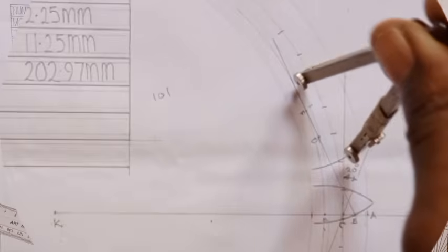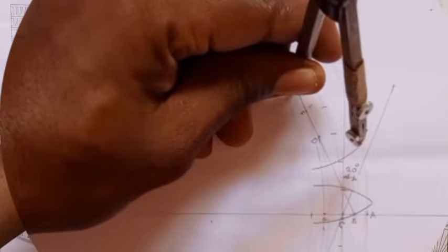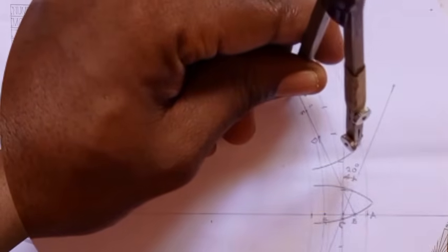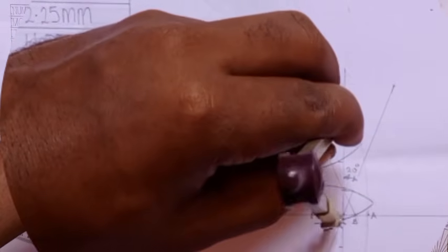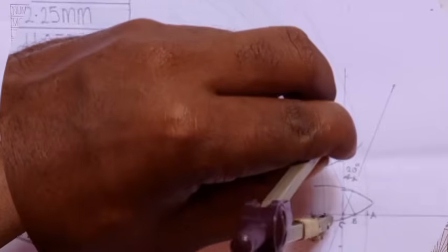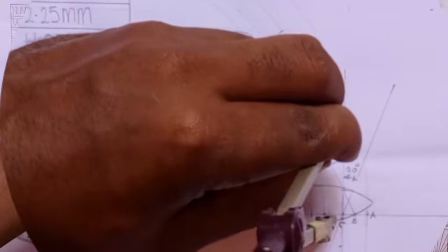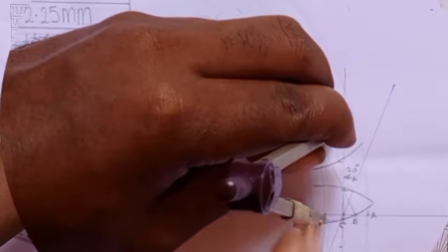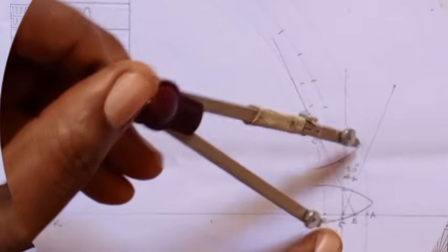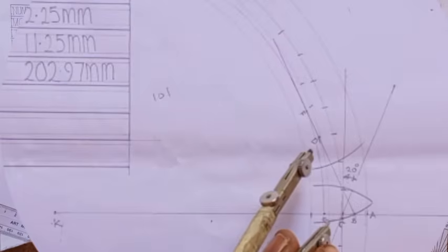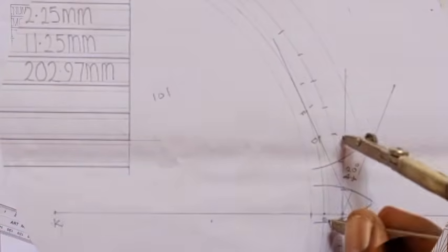You can see that? Now look, the pencil now is facing the right hand side here. So I'll still come to the second point again. I'll mark on the right hand side on that radial line again. Right? If I mark it, I'll now turn it. Look, I'm turning it here. I'll turn it to that point and I'll place it here with the same measurement. And I'll draw another arc again.